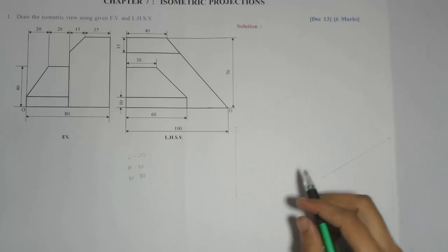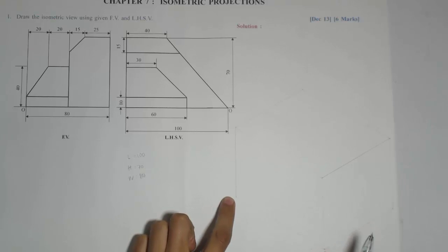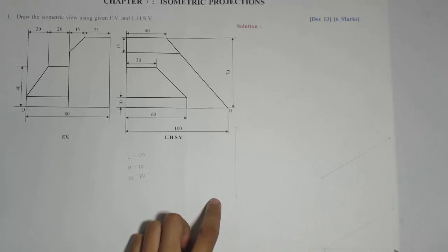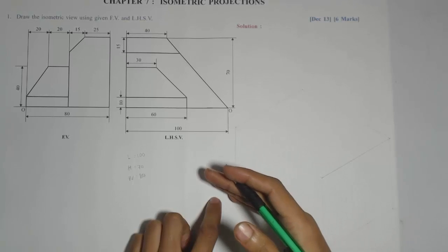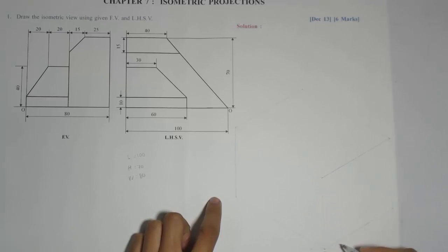In this box we have one dimension as length, which is 100 mm. The procedure for drawing this box is, first you mark a horizontal line, then you fix an origin O. I'll tell you how to mark this origin. Then on one side of this origin you mark 30 degrees, then the second angle will be 90 degrees for marking height, and on the other side you mark again 30 degrees. So these angles are 30 degrees.